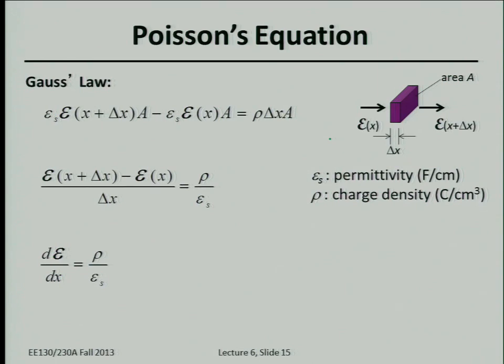It's higher here at the top where there are more electric field lines, and going from up here to down there it is decreasing. That's all that Poisson's equation says: if electric field strength is changing, you must have some charge in your semiconductor.